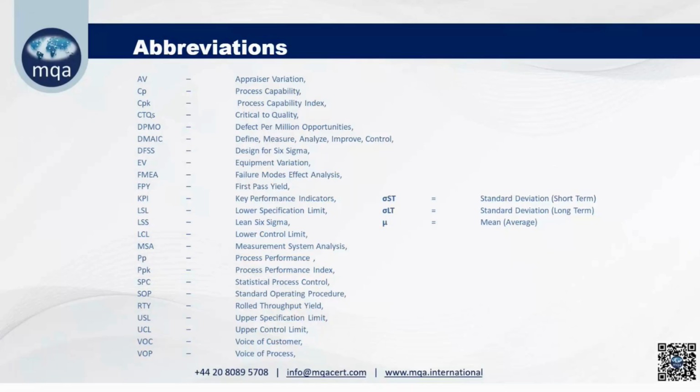Now the control limits we have to find out. How do we find out the control limit? With the formula. CP is equal to tolerance upon 6 sigma. Okay, this is the formula. CPK is equal to USL minus X double bar upon 3 sigma, or X double bar minus LSL upon 3 sigma, whichever is minimum. Okay, now this is USL, LSL.